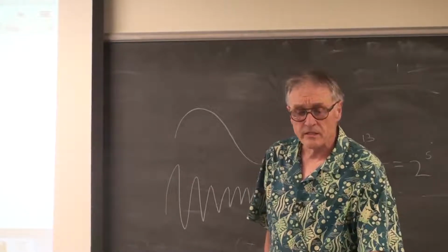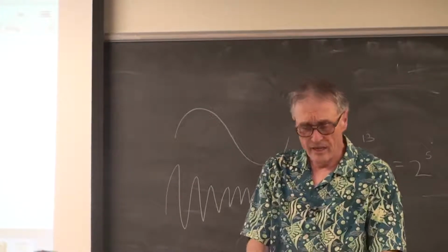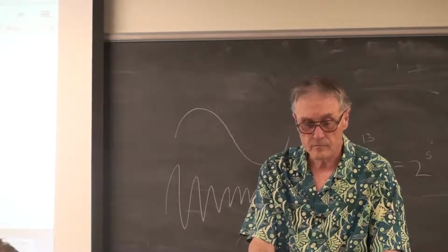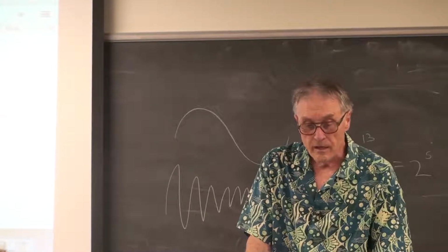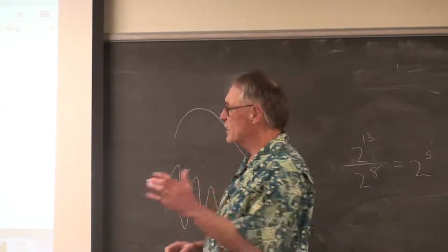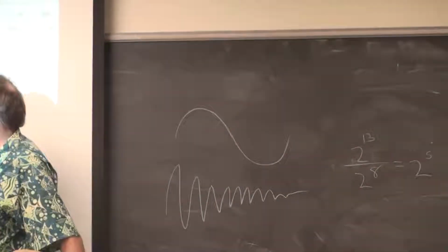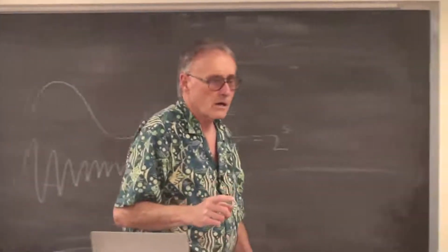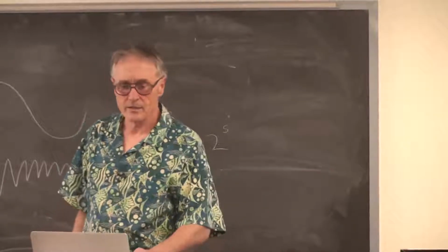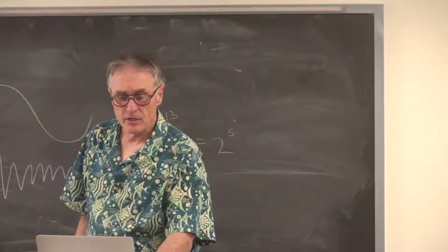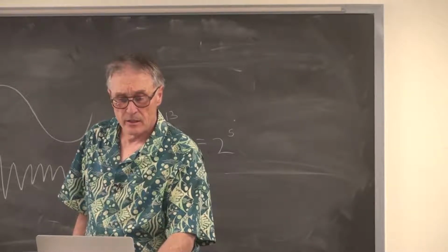So it's successive approximation. It is ten bits, but to get a megahertz actual conversion, to get a megahertz into memory, you must use direct memory access. You can't actually take interrupts at a megahertz. So you have to do direct memory access. There's actually 9 inputs on our package.